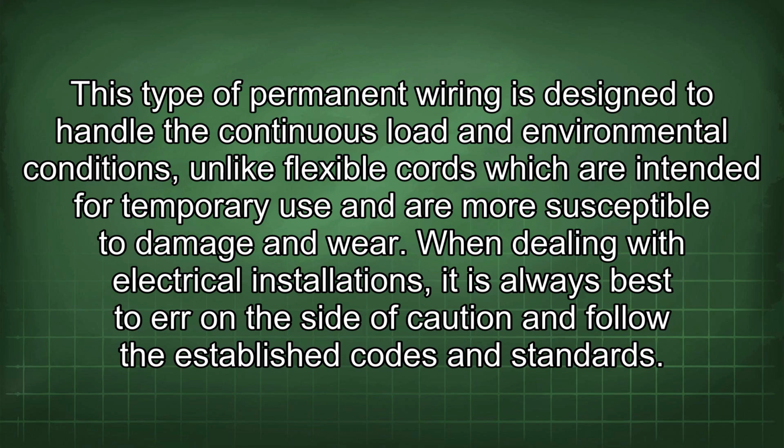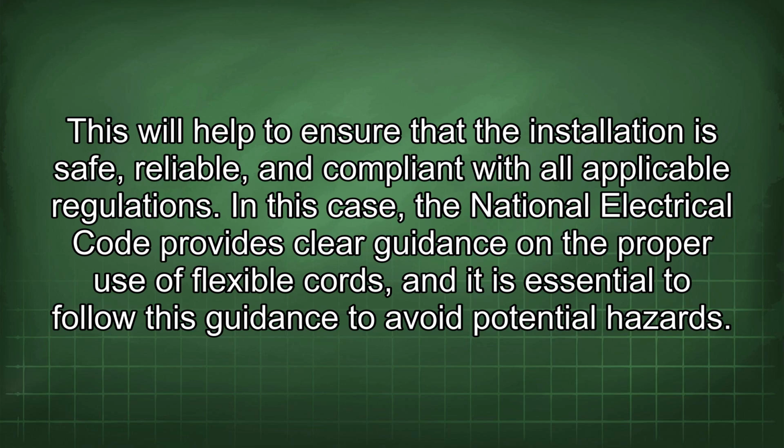This type of permanent wiring is designed to handle the continuous load and environmental conditions, unlike flexible cords which are intended for temporary use and are more susceptible to damage and wear. When dealing with electrical installations, it is always best to err on the side of caution and follow the established codes and standards. This will help to ensure that the installation is safe, reliable, and compliant with all applicable regulations. In this case, the National Electrical Code provides clear guidance on the proper use of flexible cords, and it is essential to follow this guidance to avoid potential hazards.